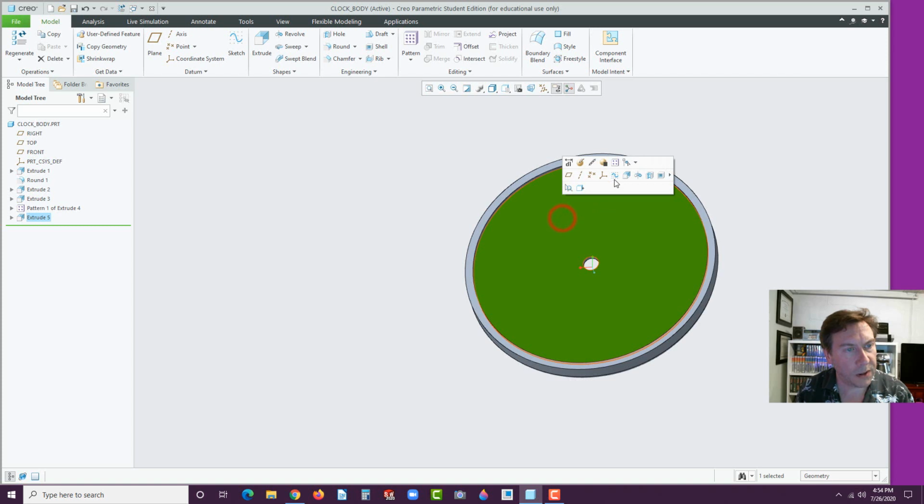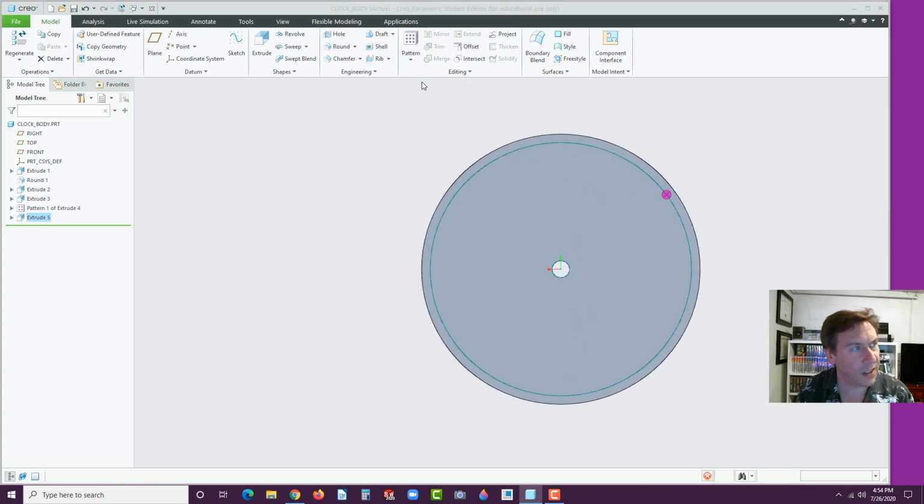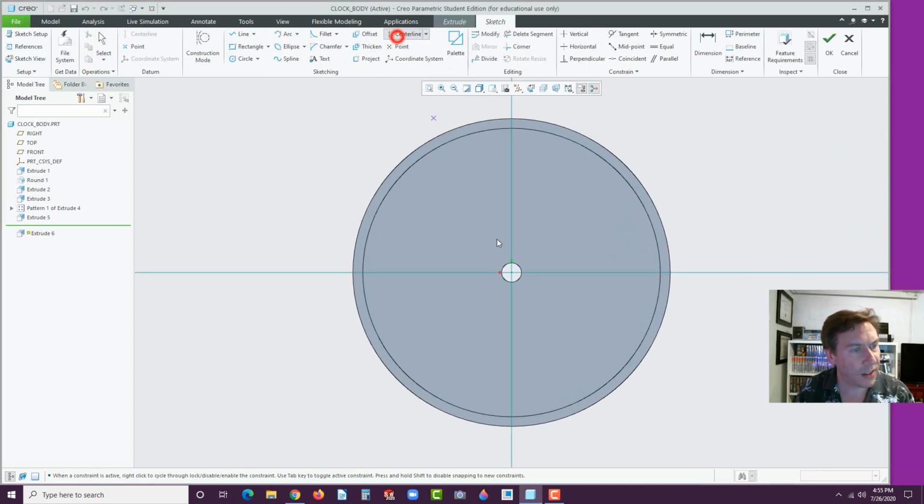All right, now you have to put in 4 prongs. Select this face. Go and add center lines, a vertical and a horizontal. And the reason why is that we're going to mirror those. Add your circle here for the prong. Let's go to 0.125, actually 0.25, sorry. And then it's 1 inch off of center for both vertical and horizontal dimensions.